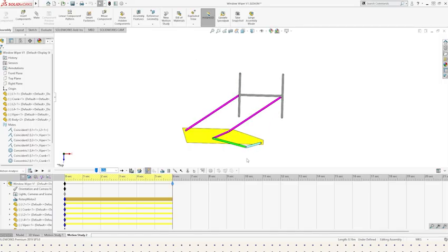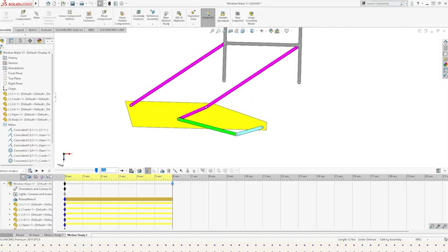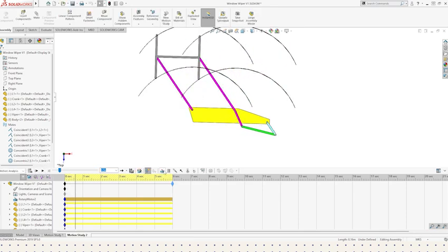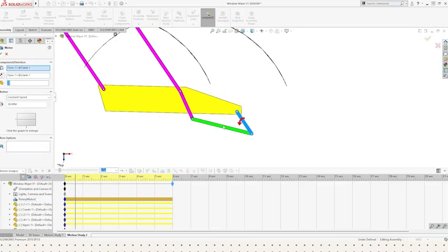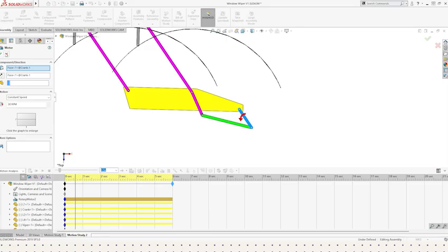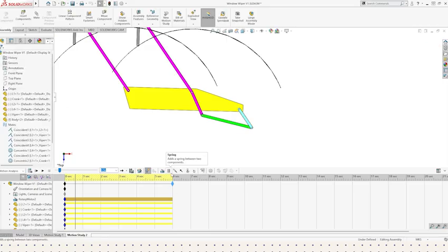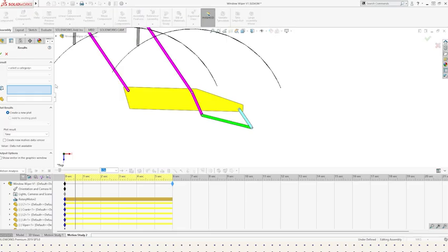Okay, so how is it done? We can see the traces of the path. We have used a motor that is attached here to perform the rotary motion, and then we can see it is rotating in an anti-clockwise direction at a constant 30 rpm. And then there's another great feature of SolidWorks, that we can perform motion analysis and obtain graphs of various things. There are displacement, velocity, acceleration, and forces that can be extracted. The momentum, energy, and power can also be calculated.